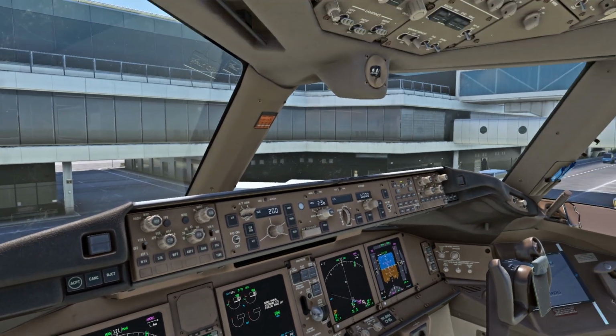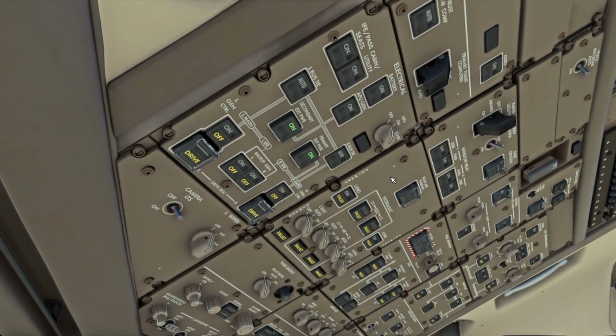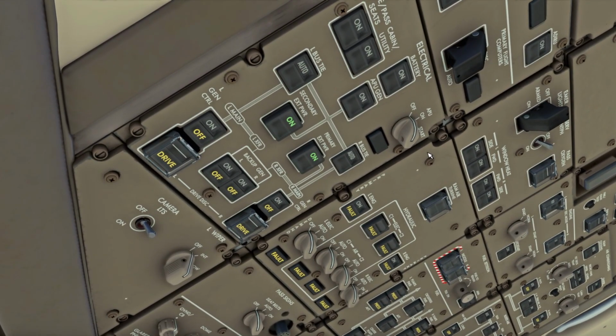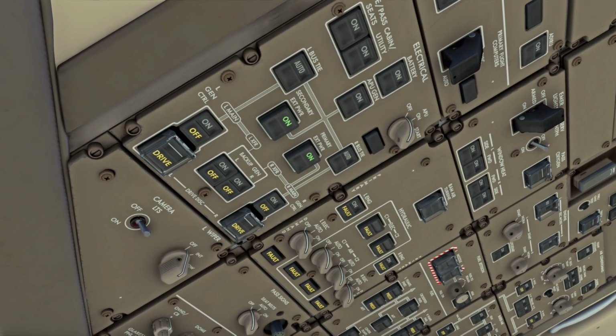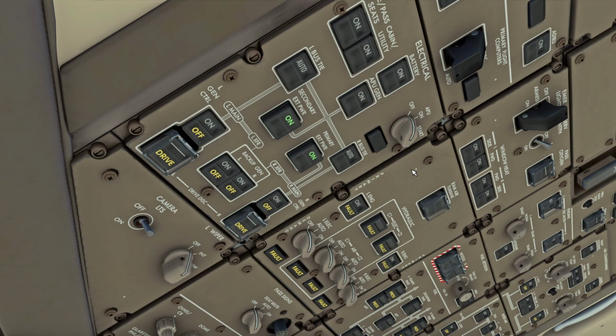Now a few minutes before departure, you would also start up the APU, the auxiliary power unit. It's a little engine in the tail of the aircraft that will help provide some electrical power. "Departure checks completed. Bypass pin inserted." That's the ground crew, and that's good to know. All the checks downstairs have been completed, and the bypass pin has been inserted.